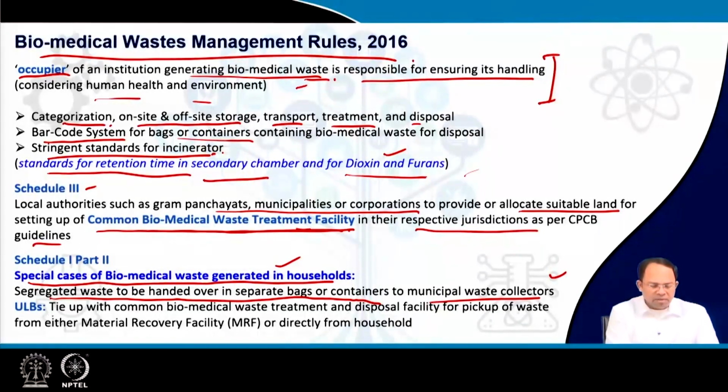Now, the municipal waste collector, or the ULB you can say in this case, can have a tie-up with a common biomedical waste treatment and disposal facility like over here, and these people can come with their own vehicle and pick up the waste from either the material recovery facility or even directly from the household, and then take the waste for proper treatment in that facility.